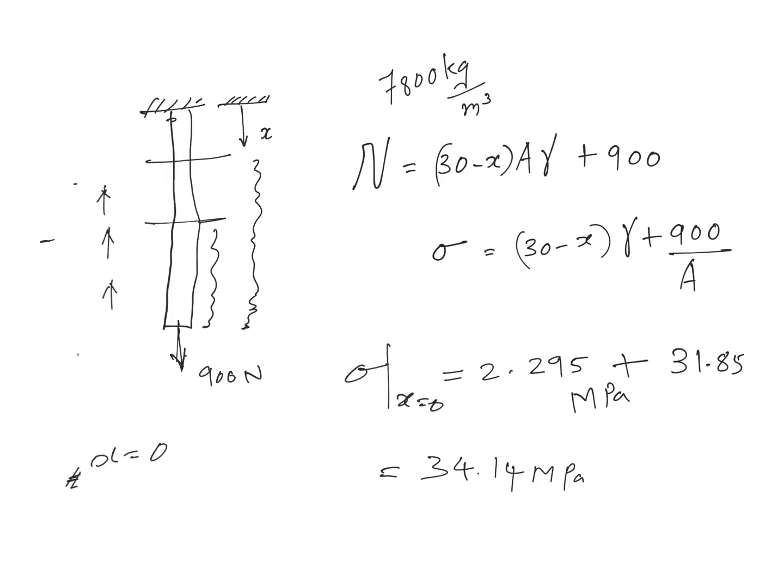So that stress value you can easily compute once you plug in x equal to 0 in this particular expression, and the value will be around 34.14 megapascal, where the bulk of the contribution is from the point load, and there is a contribution of 2 megapascal from the self weight of the bar.